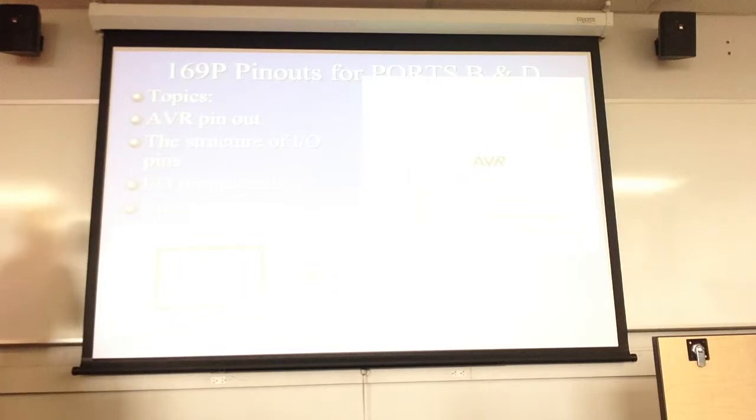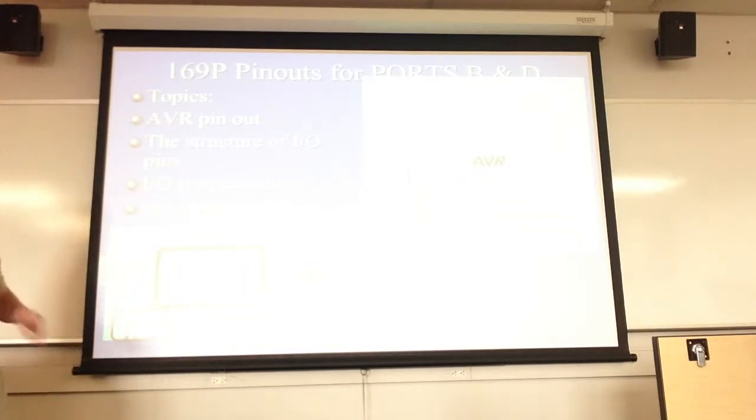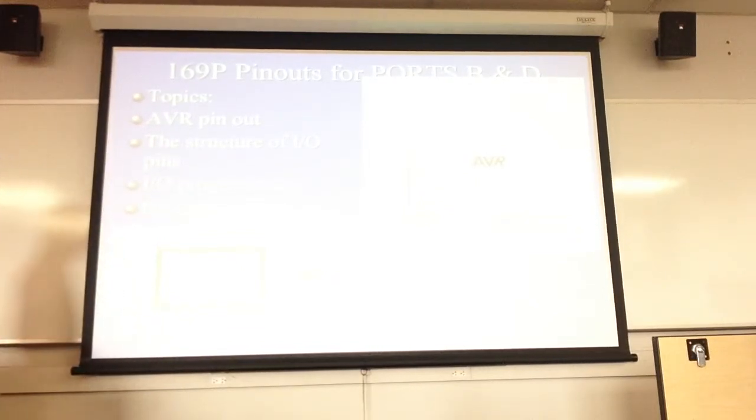Your lab this week will be using stack and simulating I/O. Next week you're actually going to tie some LEDs and stuff up to here and start doing some real I/O. Port D on your quad flat package is tied over here on those pins on the Butterfly board. So we're going to be working down here with these I/O registers, which are your special function registers. That's what we're going to be looking at.